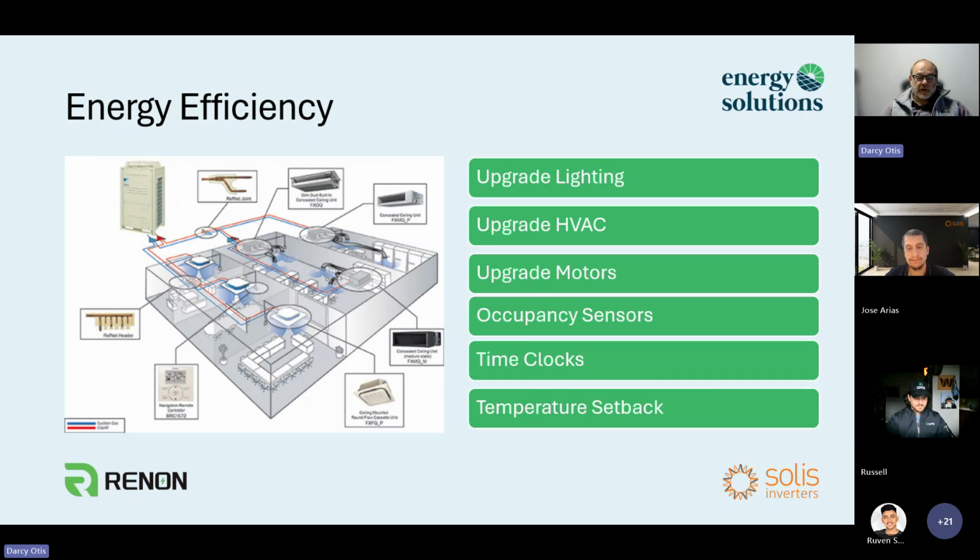That impacts both your demand as well as your consumption, and potentially even power factor costs on components of the bill, because older technology uses magnetic ballasts, which is an inductive load and can be large in a large facility.